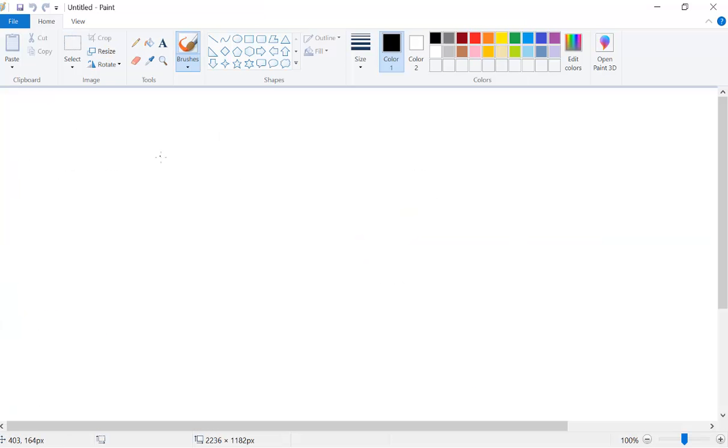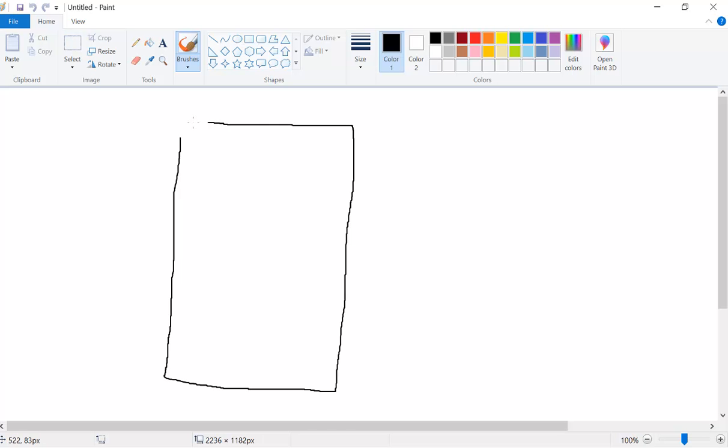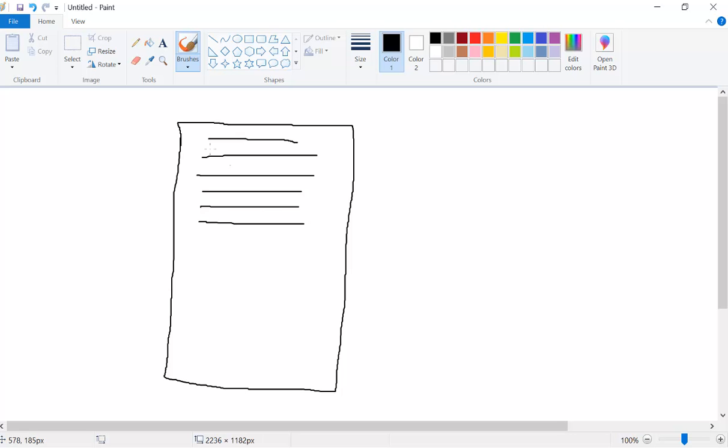The C or C++ code is converted into machine code, which is just 1s and 0s. If it's an 8-bit microcontroller, for example, here's a memory. The instruction memory stores all the instructions in 8-bit form, line by line, and each line has an address. And there will be an address decoder to take out every instruction one by one. So that's why you need a loop. If you want to keep blinking an LED or keep running the same thing, you need a loop in Arduino. Okay, so that loop will be executed forever.